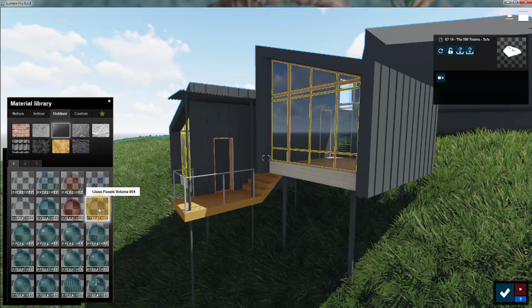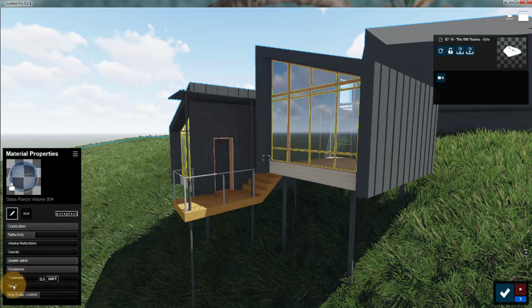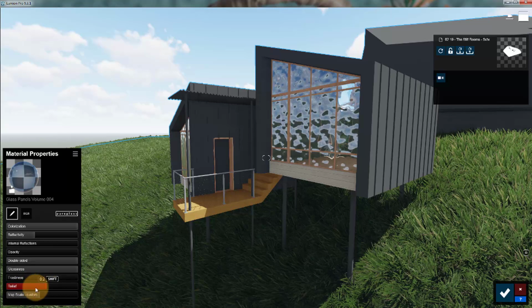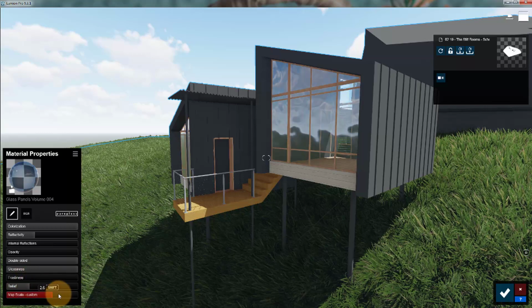Little tip for everyone here that I like to show when I'm teaching Lumion is if you double click the pure glass, you have a bunch of nice settings. One of the settings that's really cool is called relief. I'm going to make it really dramatic here, but for those of you who have followed my blog over the past few years, you'll notice I have a glazing technique inside of Revit that basically does the same thing, because as you all know, when you look at the reflection of glass, it's very rarely ever a perfect sheet of glass. There's usually some convex or concave to it. So what you can do is you can actually change the relief and then bump up the scale.